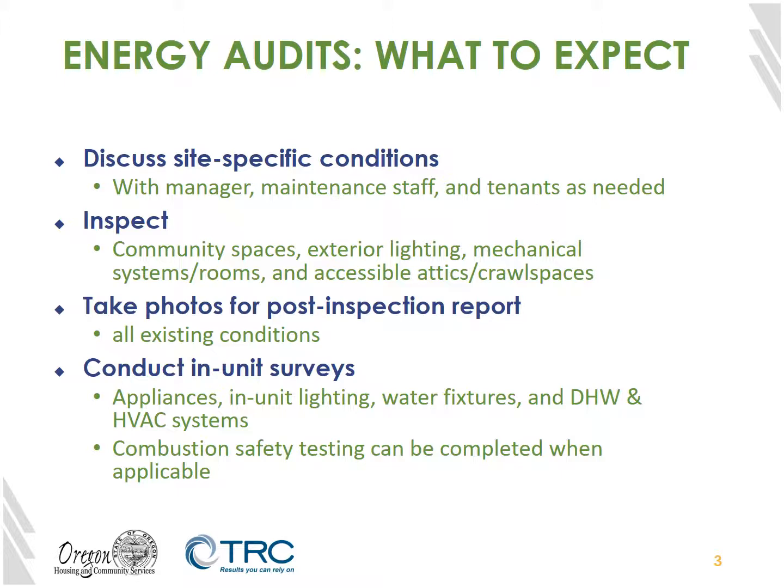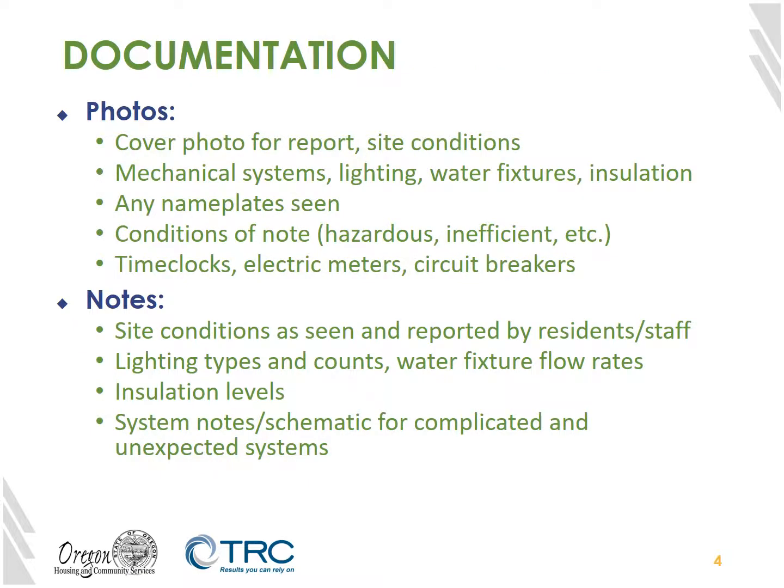Throughout this process, the auditor will need photo documentation of all equipment and conditions seen, particularly nameplates and other identifying information of equipment. While at the site, the auditor will need to keep in mind that photos will be necessary both for later confirmation of equipment types and conditions and for delivering recommendations to the property owner. Therefore, photos should include technical details of equipment as noted, in addition to general overview shots of the site and existing equipment. Care should also be taken to photograph controllers, meters, and circuit breakers when possible.